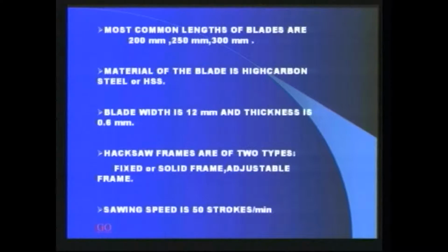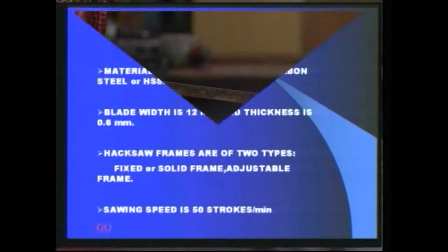Over tension on the blade, too rapid cutting and excessive pressure are causes of broken blades. For harder materials, it is necessary to saw slowly and to use greater pressure.